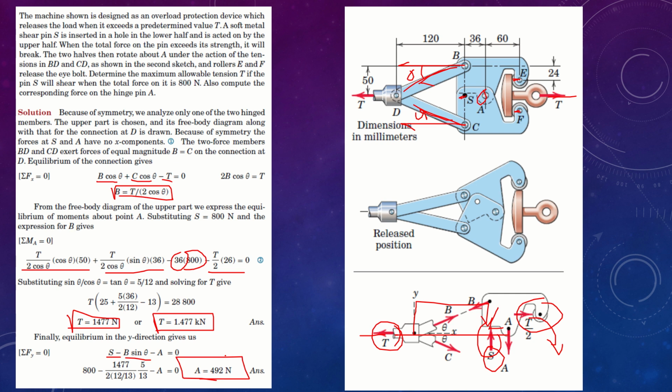You have to understand, we have isolated each member and we have created how the forces are traveling from each element to another element. As you know, a roller provides only one reaction. It does not allow moments.